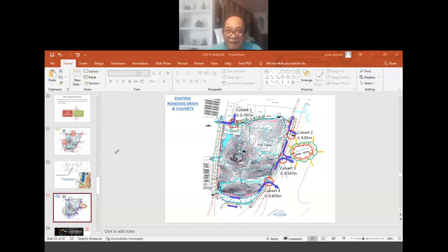There are cases where we have a drain from a higher level connected to a drain at a lower level, where the difference between these two levels is quite significant. For this purpose, what we provide is a step drain. Not just a single drain, but a step drain where it steps down around 200 to 300 for each step until it reaches the lower level of the drain. From a higher level to a lower level can be discharged using a step drain.